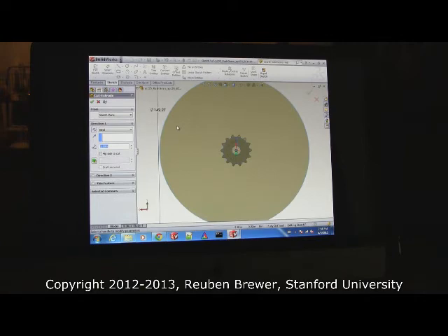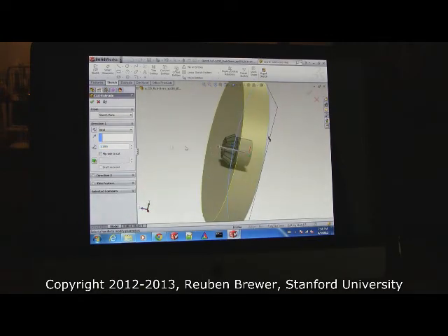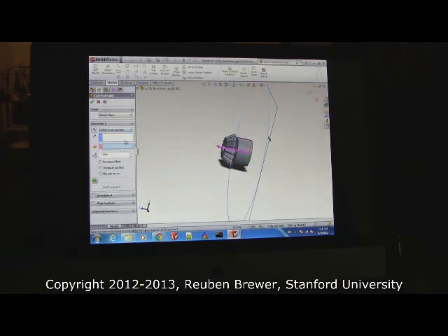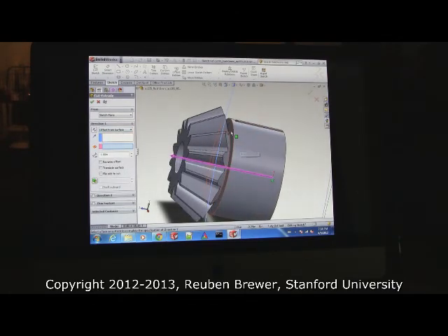Okay, this is a new type. Rotate here. Offset from surface. Over here. And now click this surface. And now make it 8 millimeters. So that's 8 divided by 25.4.